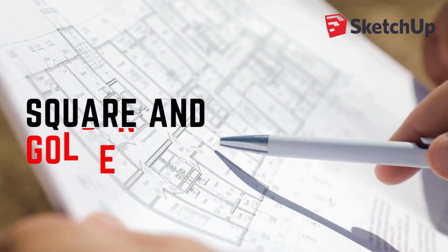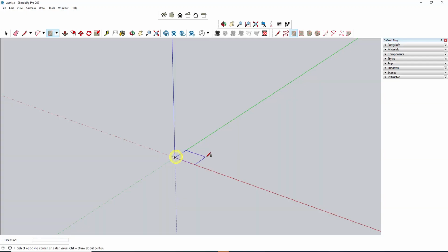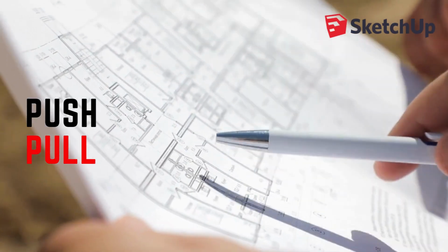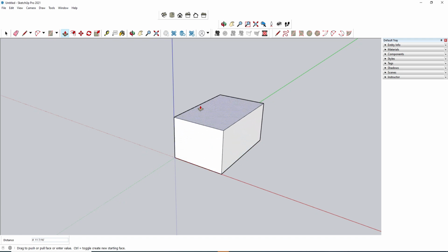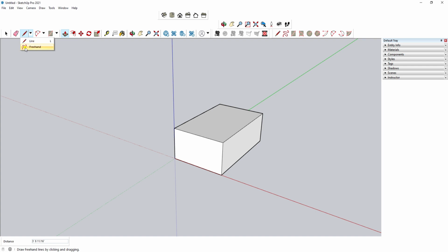Square and golden section. Simply activate rectangle and start drawing. SketchUp lets you know when the cursor is in a position to create a square. If you click when you see the indicator, you'll create a square. Push and pull. Push-pull is what makes SketchUp so unique and easy to use. Simply put, it takes a face and makes a 3D assembly of faces. Freehand. It is used to create freehand sketches.